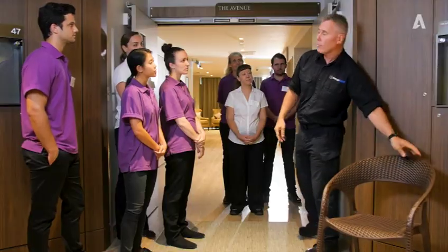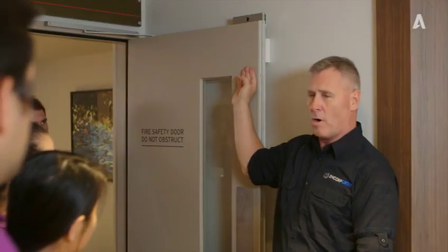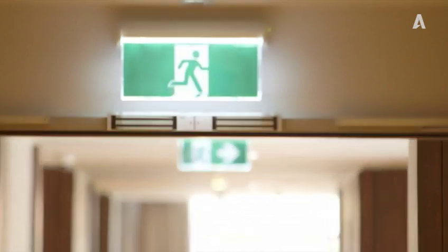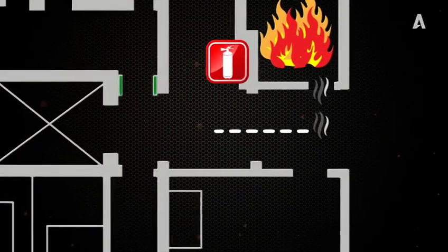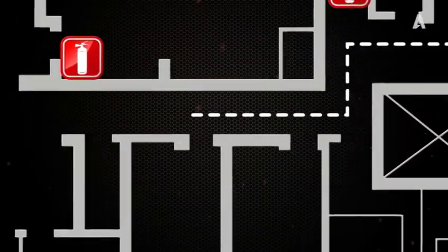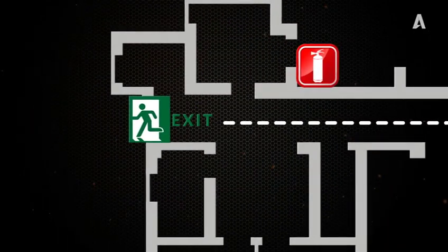How did the doors work? This one has an electromagnetic device that is linked to the home's fire alarm system. The device closes the door during a fire situation. The doors are part of a system of compartments designed to prevent the spread of fire and give people more time to escape. The compartments are divided by fire doors, walls and floors, which are resistant to fire and smoke.